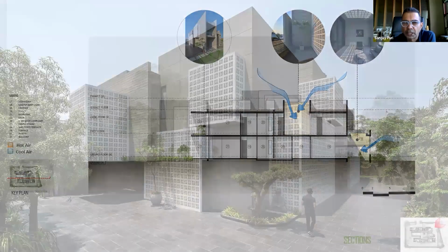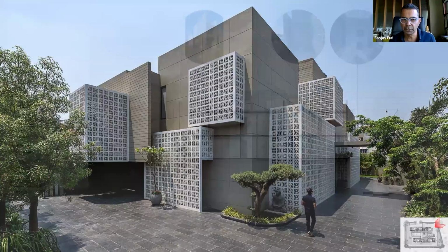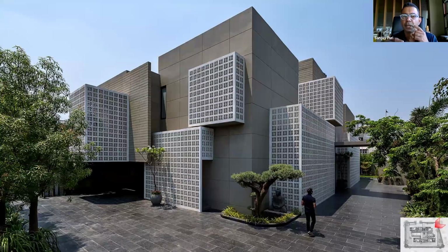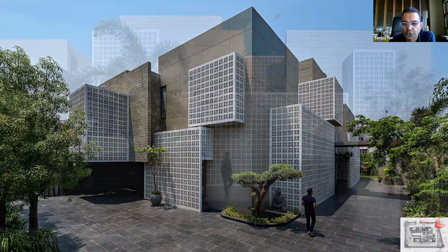And this is the house as is seen. Now, this is the first view from the southern side. So literally the house turns its back onto the main road, in a sense. And all of these are GFRC screens with a design derived from the Lucknow chikan embroidery work that Lucknow is famous for. These screens envelop all these volumes, reduce the heat gain, and reduce the sound from the main road that the house sits on.